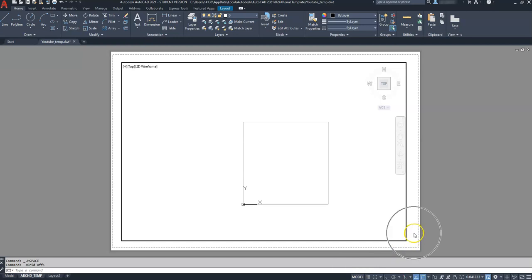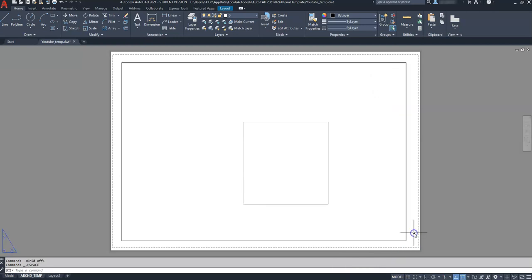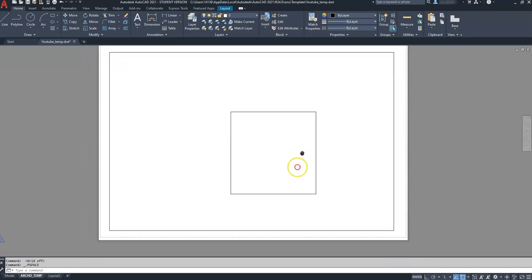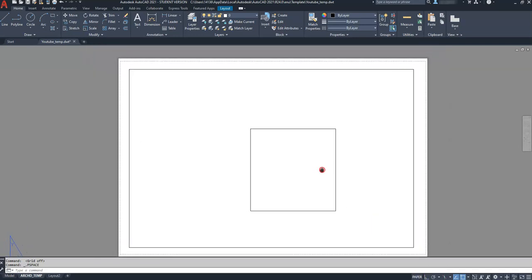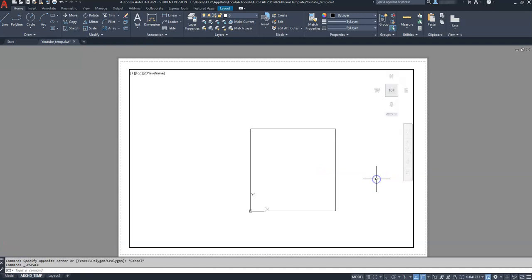So now if I click off into the white spot in my paper space here, just double click there, you'll see that I now transferred to paper space. And as I pan around, I move my whole paper. Now if I double click inside my viewport, I switch back to model space. All right, so watch what happens when I'm in model space. And I just take a line, and I'm just going to draw a diagonal line inside of there.